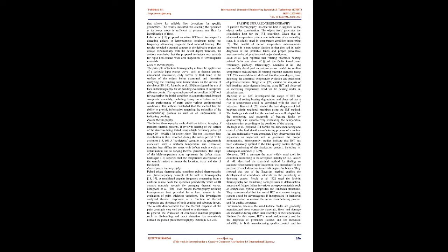Montanini and Freni investigated the correlation between the vibrational mode shapes and viscoelastic heat generation in vibrothermography. The authors found that there exists a minimum threshold of vibrational amplitude that allows for reliable flaw detection for specific geometries. The results indicated that exciting the specimen at its lower mode is sufficient to generate heat flux for identification of flaws.